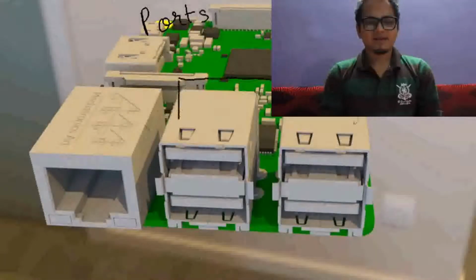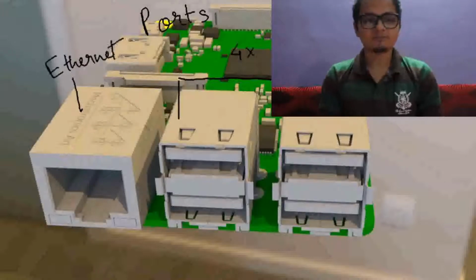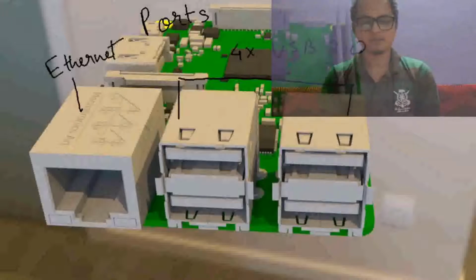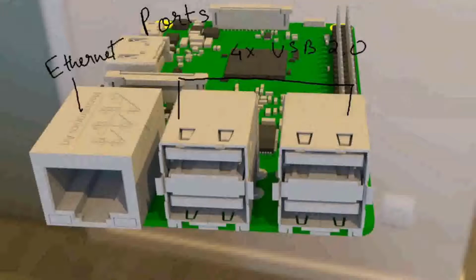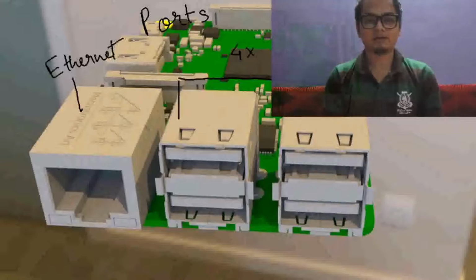Let us take a look at the components of the Raspberry Pi 3 B+ module. As you can see, the Raspberry Pi 3 B+ provides us with 4 USB 2.0 ports to connect different peripherals to it. Just beside the ports, we have the Ethernet port over USB 2.0, which provides us with a maximum bandwidth of 300 Mbps, which is a lot for a small computer such as the Pi.